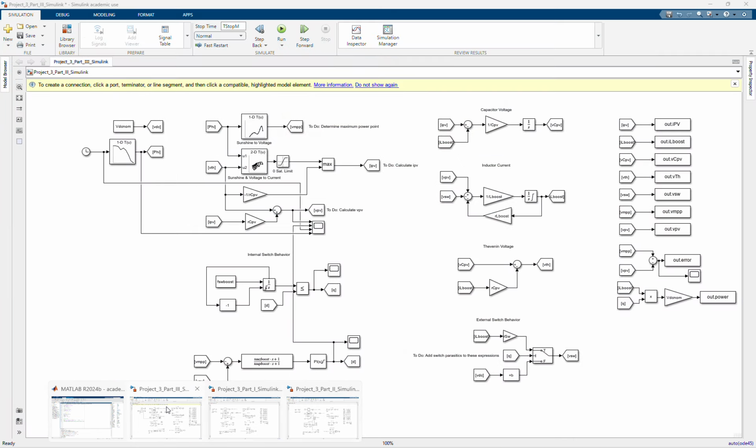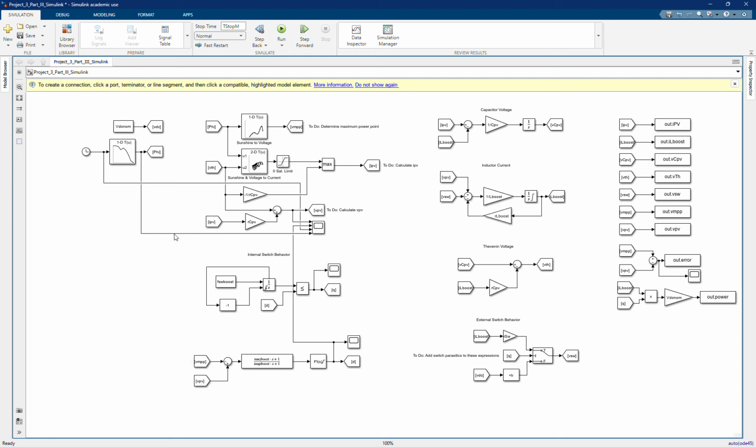Then we get on to part 3 of the simulation, and for part 3, I had to load in a few values for this lookup table. VDC nom returns to constant, which is why it's a constant block again. But this one is based off of a lookup table, and going back to adding data to the lookup table to get rid of transients, because this data starts at a specific value but then immediately begins to change. I added a few values to assume that it was at that starting value for a while to allow the capacitor, the inductor, all the circuit components to achieve steady state.